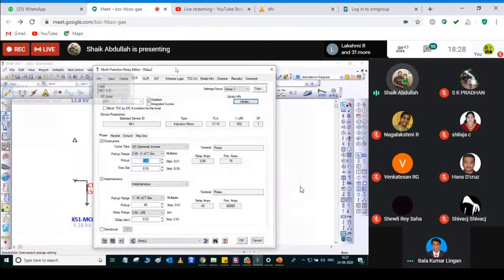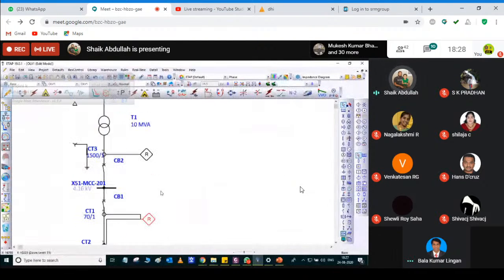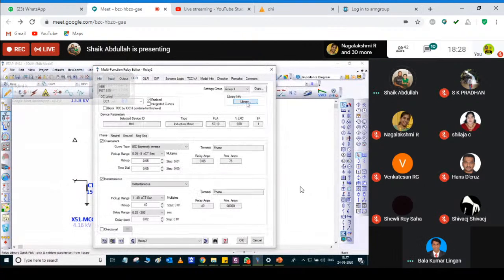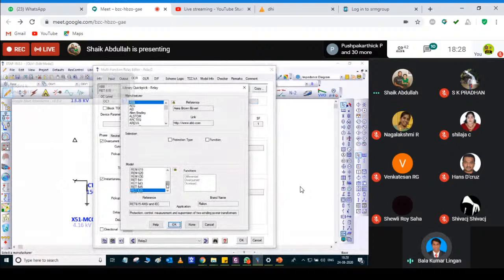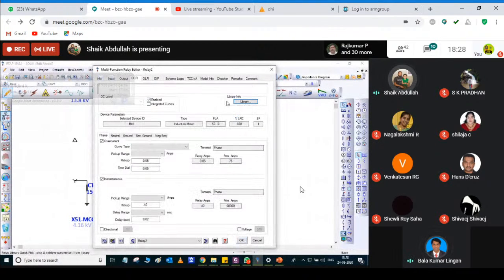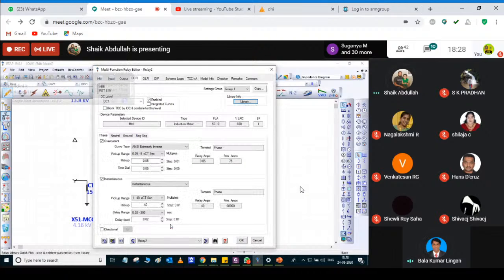The relay 2 is still showing as a motor relay. It's not supposed to be a motor relay. This relay is a transformer relay. Sheikh sir? Yes. Sir, in that we can choose the protection type. I think the protection type is wrong, so I will change that one. From that we can pick it. I think a transformer was chosen. In the transformer overcurrent, it is filtered out, so with the filter on you can choose it.